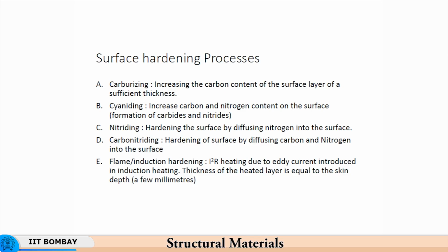Interior, if you have relatively low carbon, then the volume changes are also relatively low, and therefore the stresses which are introduced in the carburized hardened layer are much smaller. So, if you have a relatively low carbon interior and a high carbon exterior by virtue of carburizing, then you are less likely to introduce cracks on the surface.